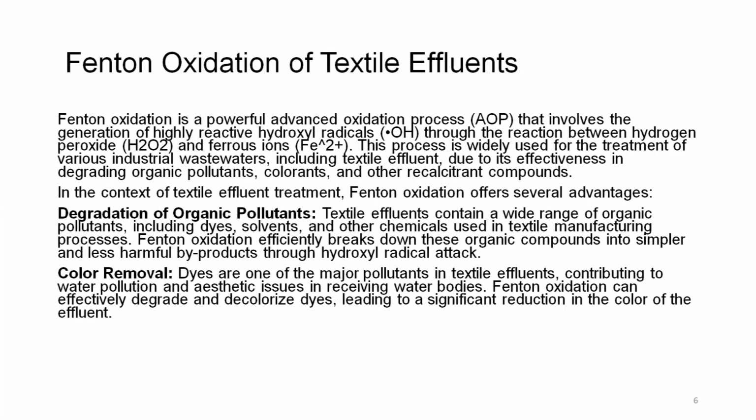Fenton oxidation of textile effluent. We have been talking about this term. Let us now see what exactly is Fenton oxidation and how does it work on the textile effluent. Fenton oxidation is a powerful advanced oxidation process that involves the generation of highly reactive hydroxyl radical through the reaction between hydrogen peroxide and ferrous ions.